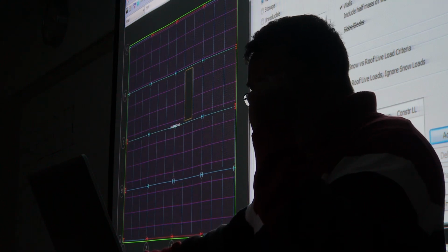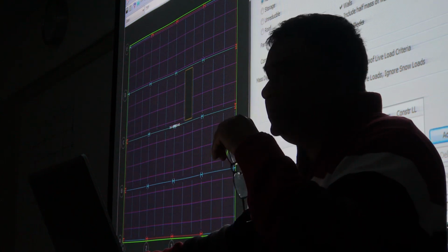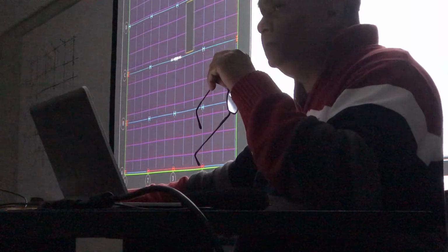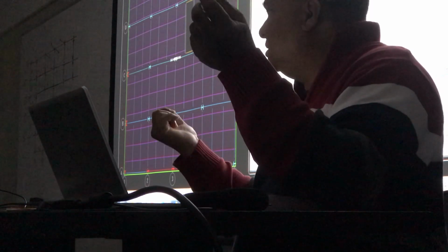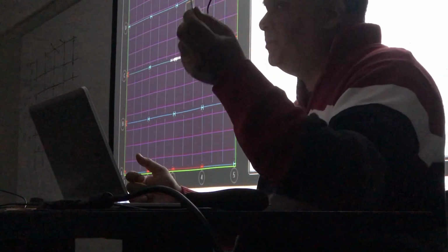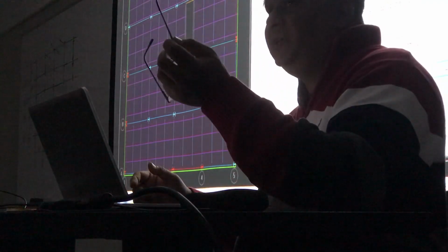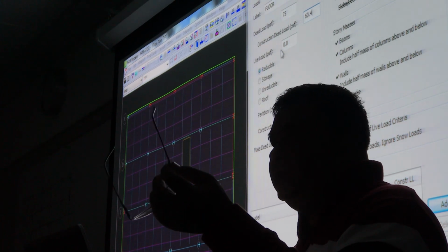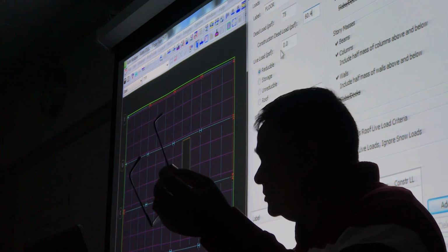Now, as I showed you, usually when we design steel structure, we don't design steel decks to take loads with shoring. Okay? Because the shoring of the decks is costly. The decks are stiff enough. It's a steel deck, so they are stiff enough to take the loads by itself. And that is why we don't span them more than 10 feet. Because if it is more than 10 feet, or 20 feet, 30 feet, the deck will collapse without shoring. Okay. So we are reducing the shoring cost, but at the same time we are adding beams in the wall.